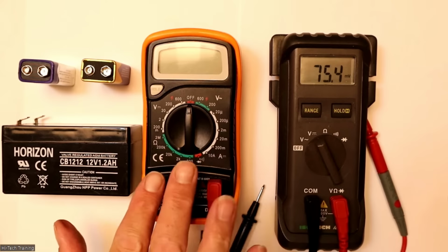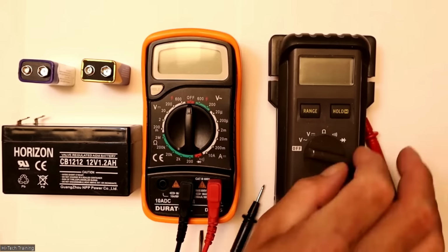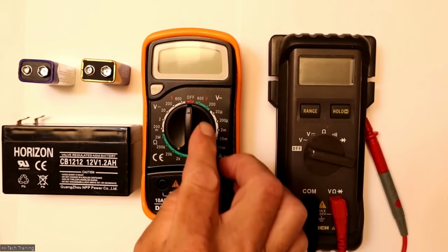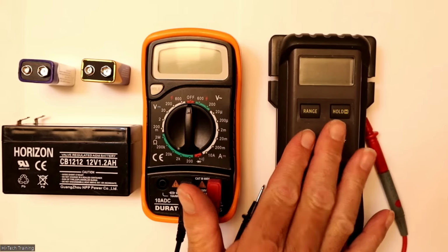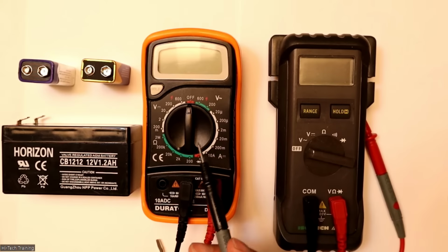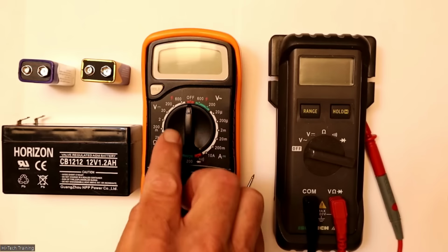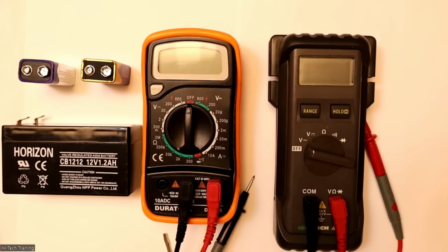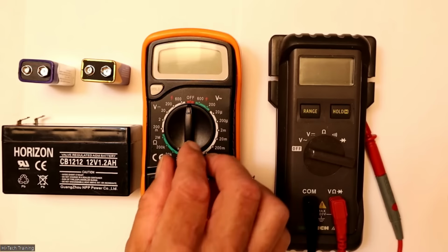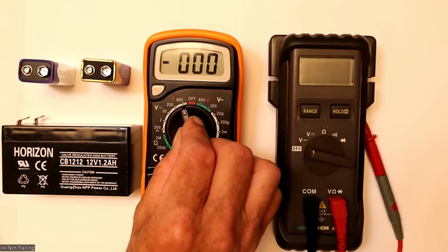So over here then on this side, we've got the standard digital multimeter, DMM. And this one, same as the digital one essentially, except you need to select the particular ranges. So DC volts over here, line with 3 dots is your DC volts. You've got different ranges here. So when you're measuring voltage, you always start in the high range and work down. So the highest range here is your 600 volts range. So that's the highest range that we can go on.